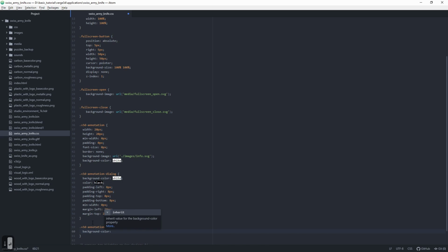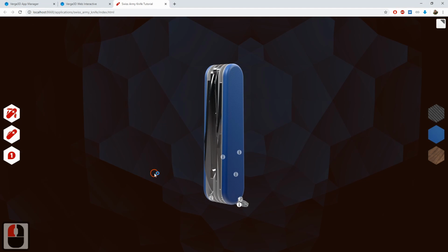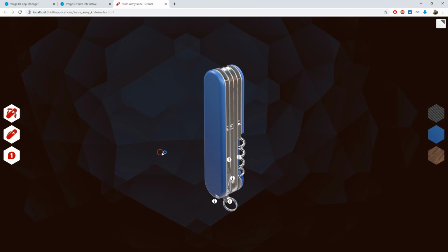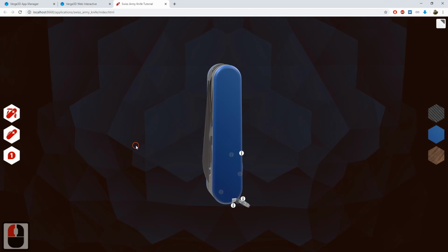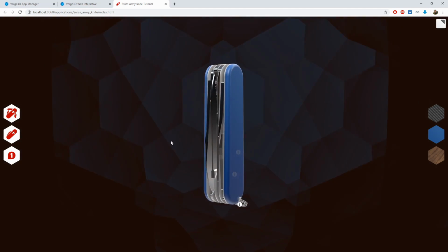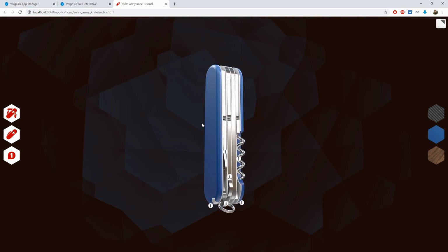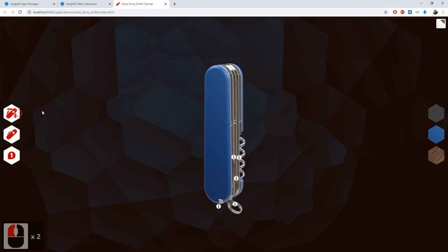First of all, make its background color gray and make its opacity value smaller. By default it is 0.5, but we'll make it 0.3. Now the difference is stark. The obscured annotations are much less noticeable than the visible ones, which is awesome.